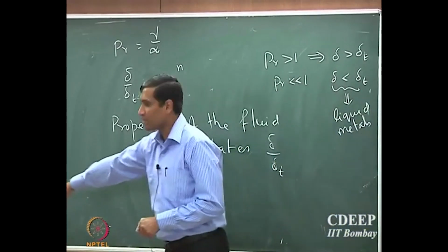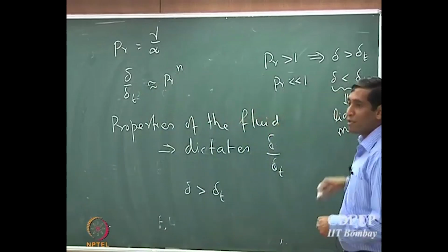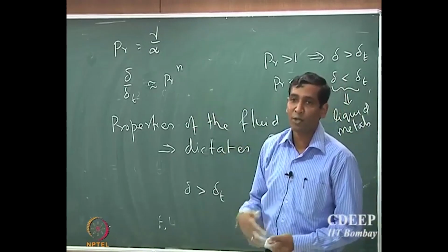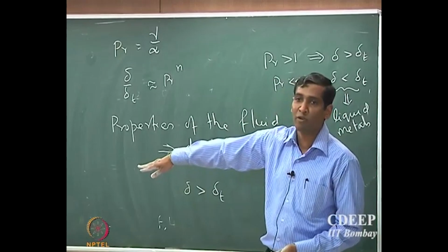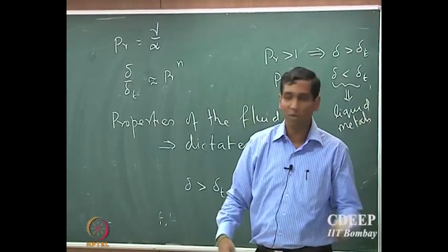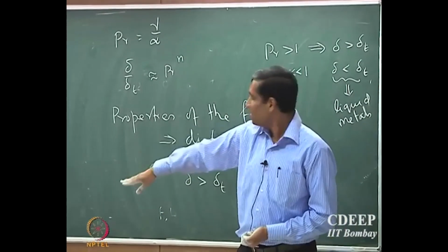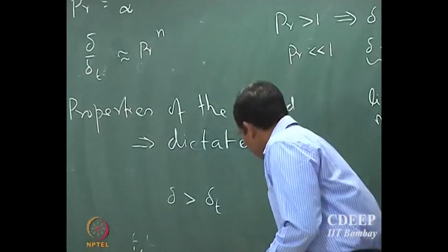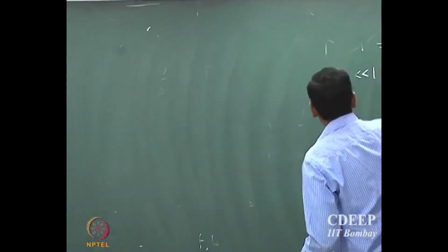So this 0.6 is a special case where if you have liquid metals in a very high temperature process, then the heat transport mechanism is slightly different, and therefore the solution falls out to be a different exponent, and we will see that in a short while, maybe not in today's lecture. I will give you the expression for the exponent n when Prandtl number is less than 0.6. Okay. So with this we can actually go and find out what is the heat transport coefficient.